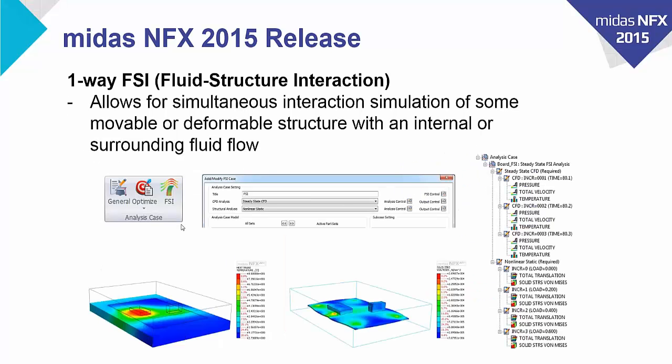So this is what the interface looks like. You have FSI type of analysis case that have been created. It's actually very simple to set up. You just have to set up separately CFD analysis like you would do for any CFD analysis, and then structural analysis, and you can link them together in this FSI analysis case.